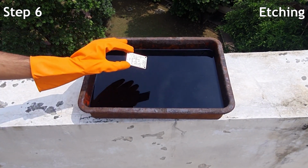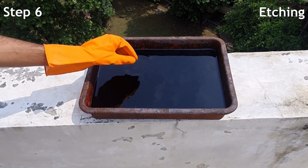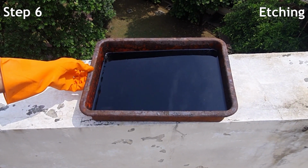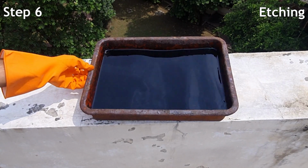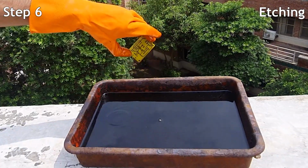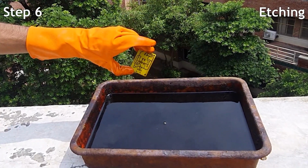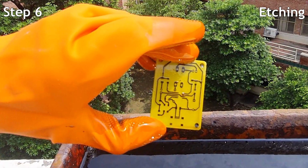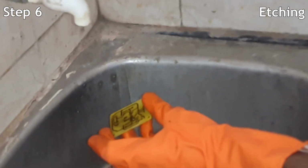Step 6. Etching. The exposed copper not protected by the toner is etched away using a chemical solution, ferric chloride solution, leaving behind the circuit traces and pads. This creates the conductive pathways that connect the components on the PCB. The PCB is then washed to remove the extra ferric chloride solution.